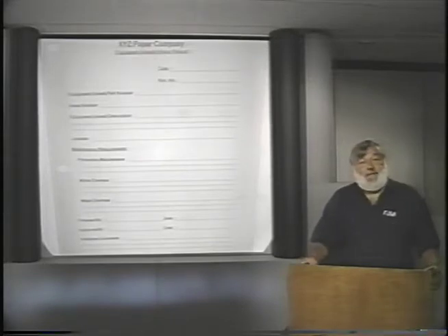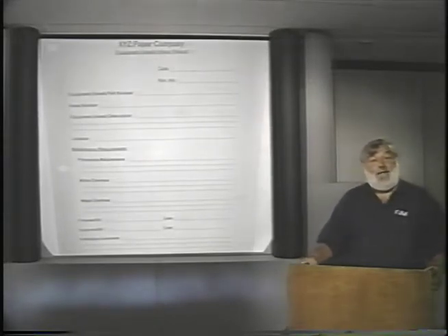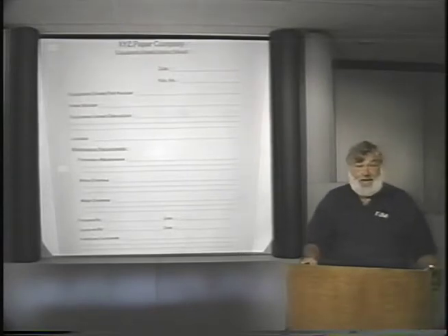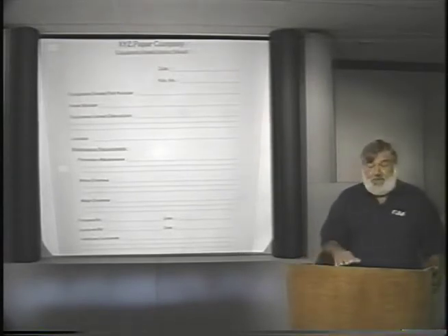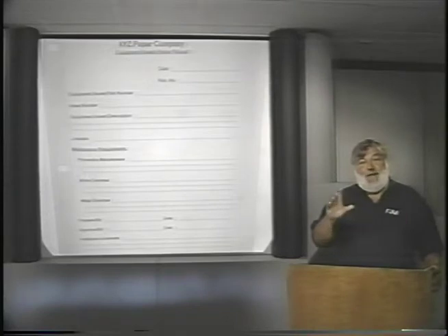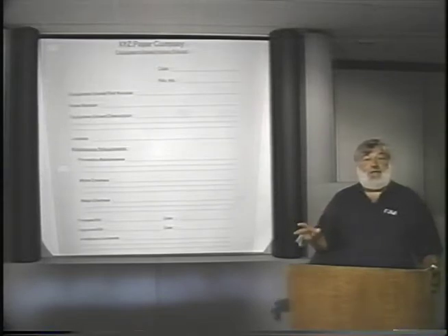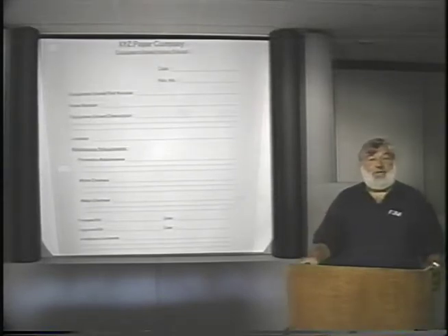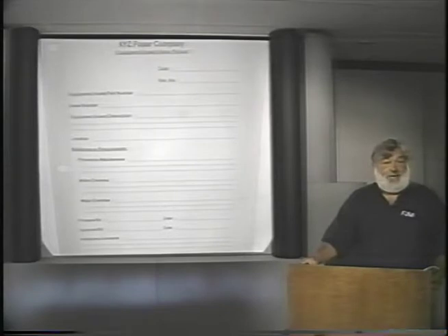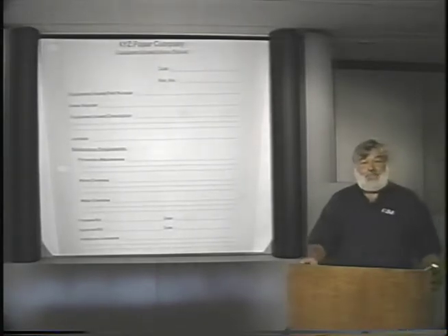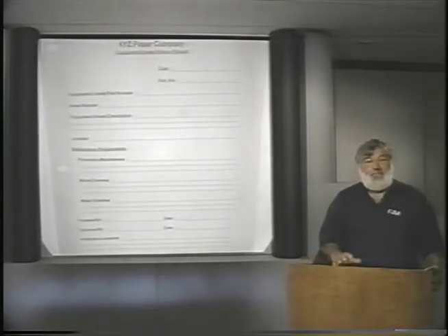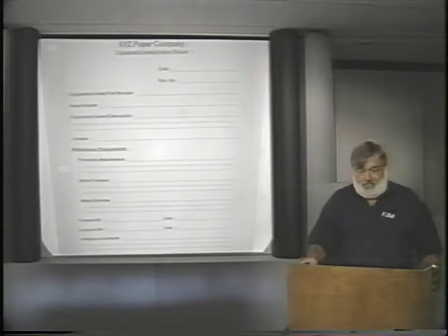If certain PMs are to be done by machine or odometer readings at certain periods of time, then you want to list those odometer readings and the machine hour readings as an indication as to when a particular PM activity will occur. The same analogy applies to minor and major overhauls.